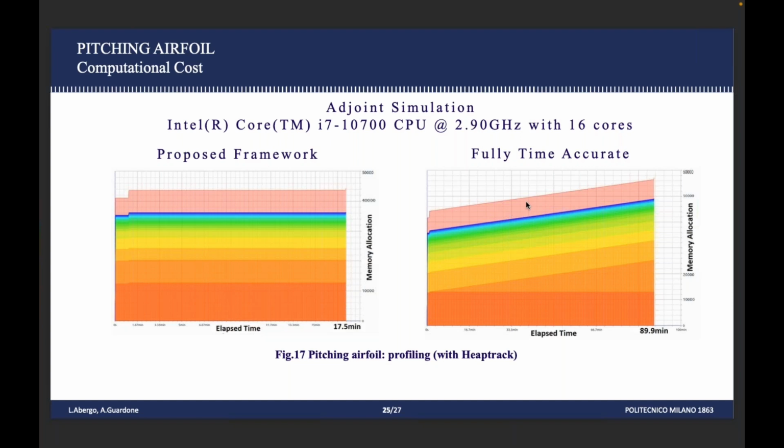Do you have any convergence issues when you do this transformation to the full time history? Because that's something typically that you will need a very converged solution for. Well, it's really difficult to make harmonic balance converge for external aerodynamics. There are just a few papers that talk about the stability of the numerical method, and it gave me a lot of trouble to find them.